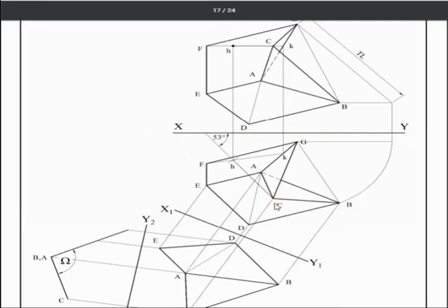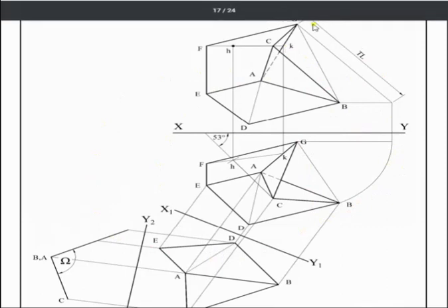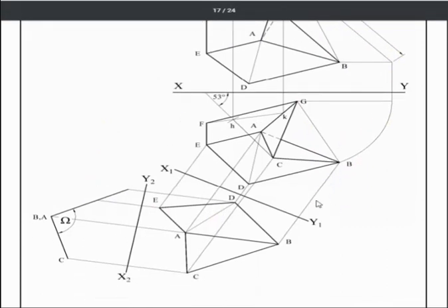A lot of the time in DCG questions, the way they phrase it sounds complicated, but it's actually quite an easy question they're asking. They want to know, this horizontal line, what angle is it making with this back wall, the vertical plane? So you just extend this and measure it here. In this case, it's 53 degrees. So this is what your answer should look like on your paper. We have the cone section here, brought out along here, and our true length put in along here. So it's a relatively straightforward question.